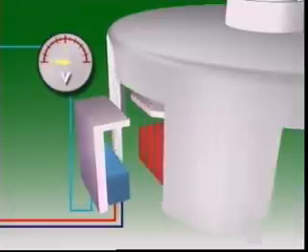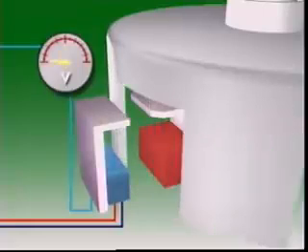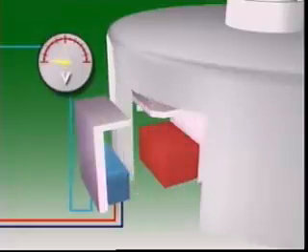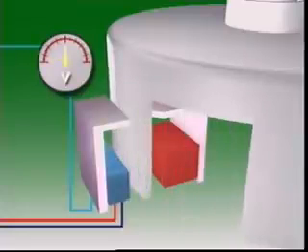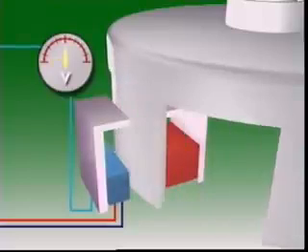With continuous rotation, the blades repeatedly move in and out of the air gap, and the signal voltage will appear to turn on and off repeatedly. The control unit uses this on-off signal to detect engine RPM and to control ignition timing.